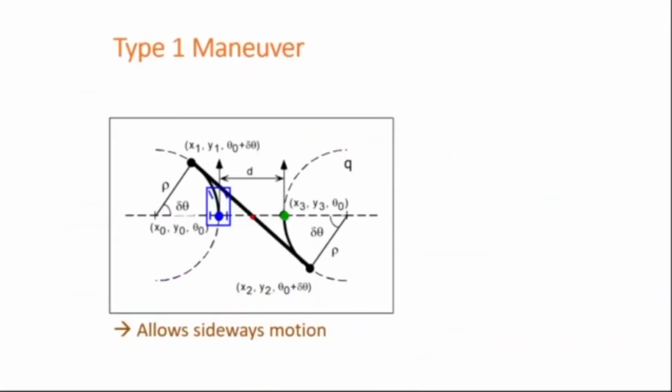It may be new, it may not be new, but I can generate more vector fields, right? So this is how we use Lie brackets to try and generate other motions, which apparently seem to be constrained by the non-holonomic constraints. So if the system like a car or a wheel is fully controllable, because they are subjected to a single non-holonomic constraint, and hence such systems are fully controllable. That's what we are told.